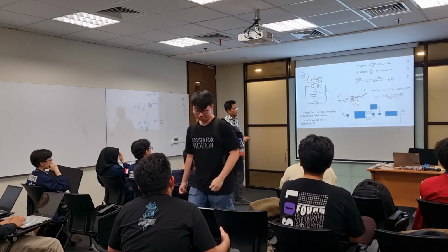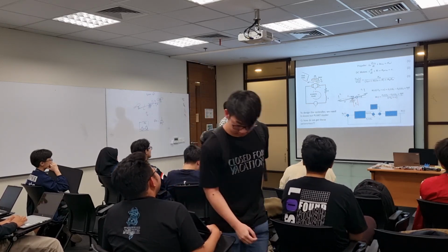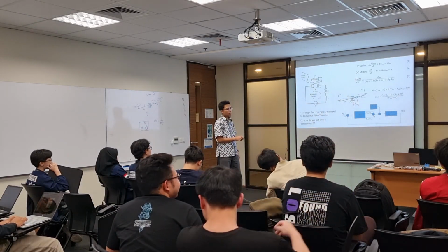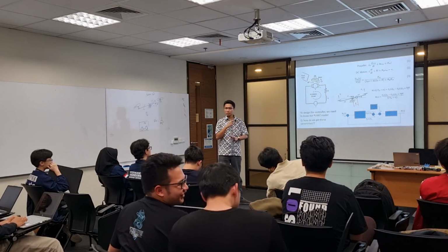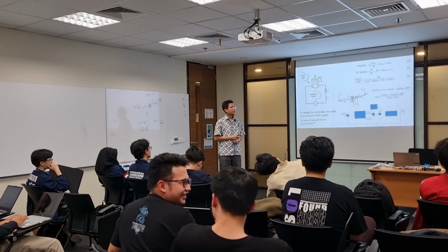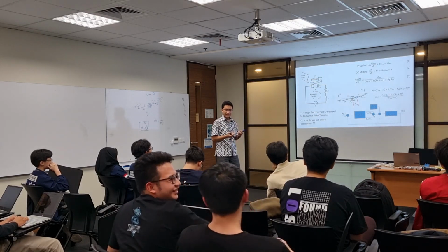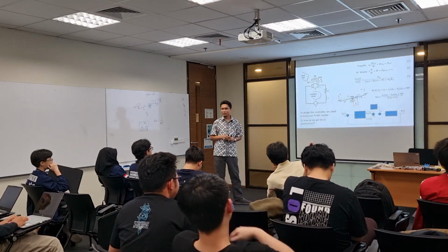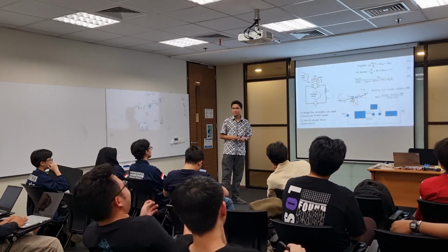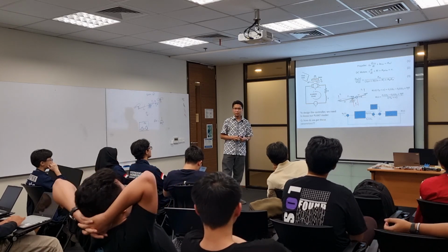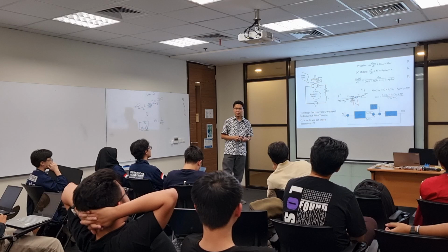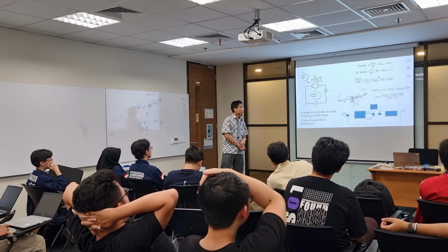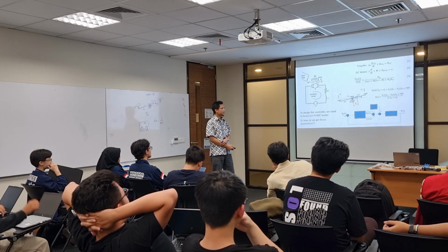So your data equation in here will be combined with this. However, from the omega to the thrust, we don't know the model yet. So if you want to be exact, you can find the thrust relationship with the omega of the motor. Will it be more complicated if we add the thrust? Yeah, because omega is not linear with the thrust. I think it will be interesting.